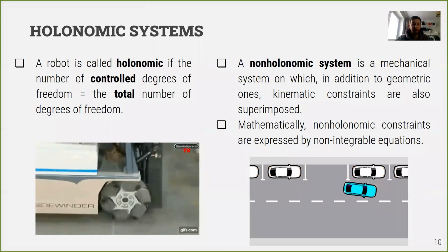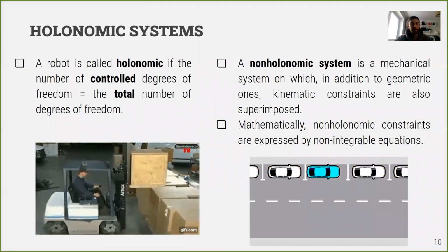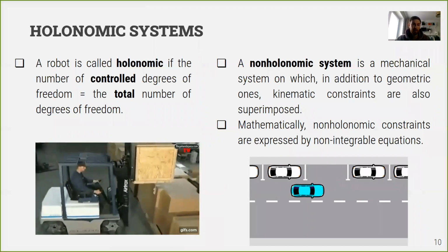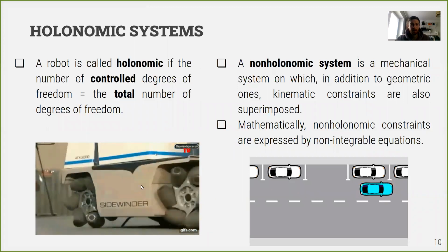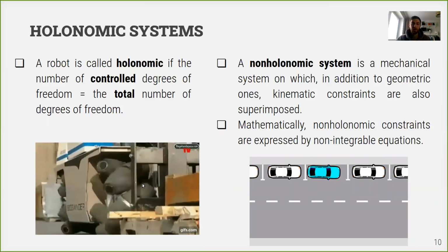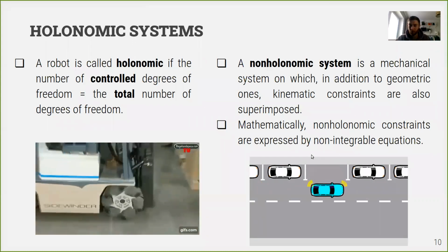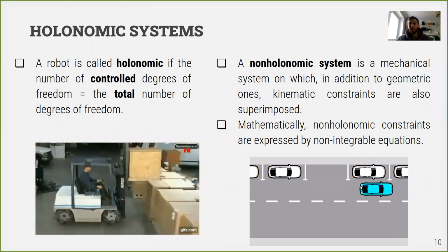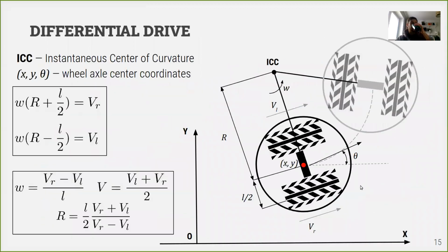It is especially important, as we already discussed, in confined spaces when you do not have enough space to make some maneuvers. It is really useful and effective to have omnidirectional wheels and holonomic kinematics, which allow you to move any direction without performing such complex maneuvers as you would have to perform with car-like kinematics, for example.